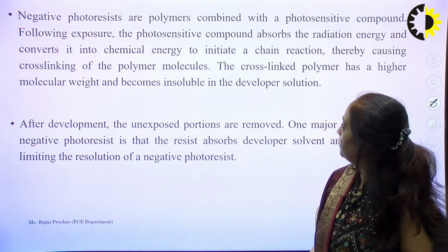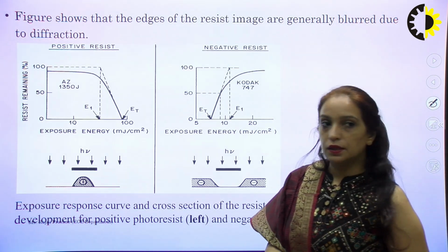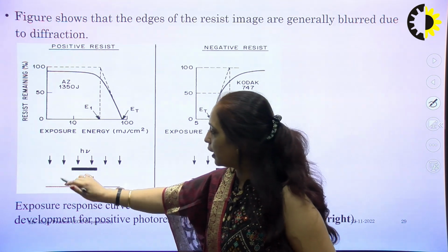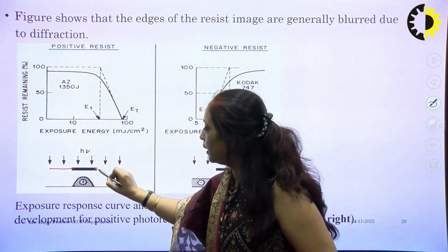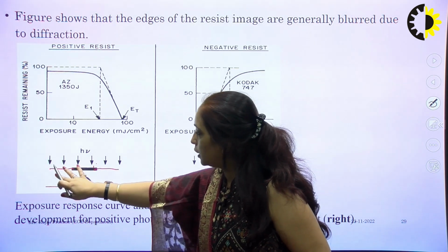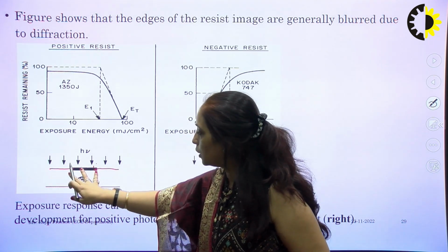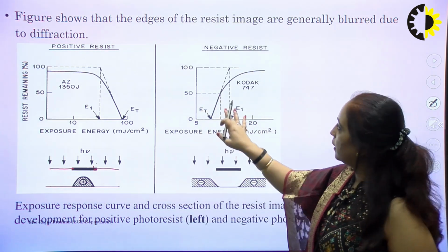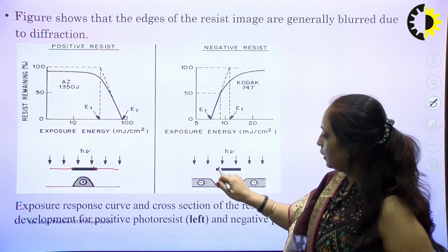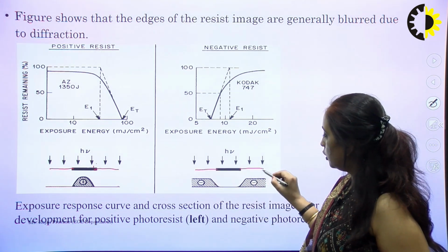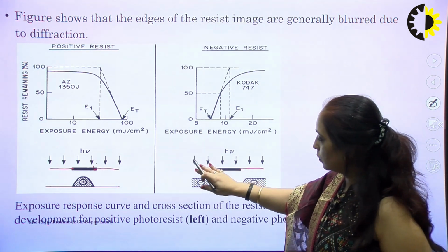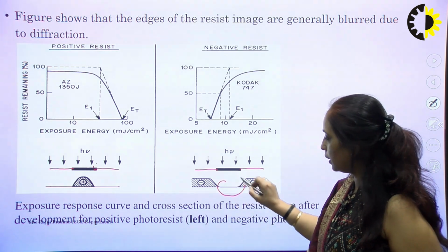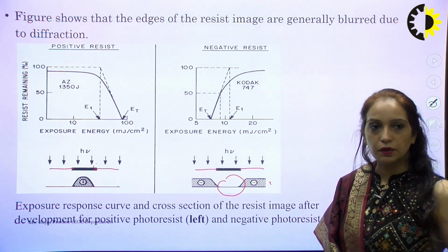So this is the case of positive and negative photoresist material. In case of positive photoresist material, here we have the mask like this, right? We have to etch from these sides, so it is protected over there, and from this side your material is etched, right? And in case of negative photoresist material, we have this mask, right? UV light is passed over this, so that portion is saved and the opposite of that is imprinted. From here it is removed, the silicon dioxide is removed from here.